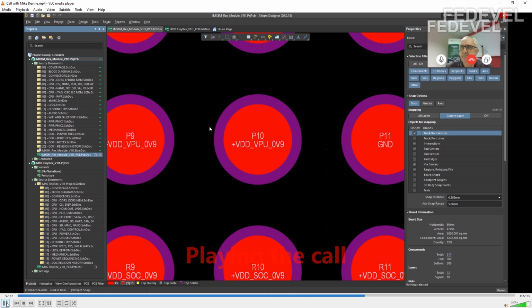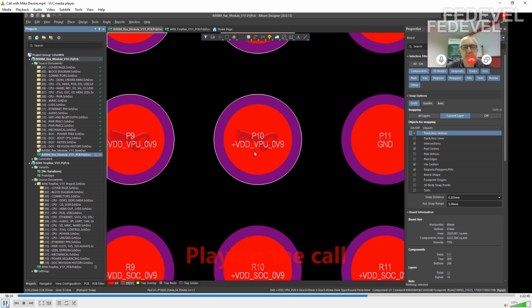That's a really good note. So basically on the top you can use lower tolerances, because you process the image and you know exactly, you can drill almost exactly in the middle of the pad. But the inner layers, you can't see them, so they can be moved a little bit. It's better if the copper is a little bit bigger. Oh, that's interesting. That's really good. I thought the machines always just drill based on position.